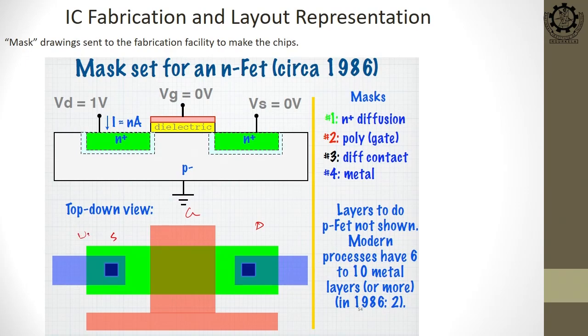So, this is your diffusion region, the source and drain diffusion, this is your gate region, that is a little bit extended, and beneath this is your actual active channel, the L, this is your L. So, if I draw the 3-dimensional view,